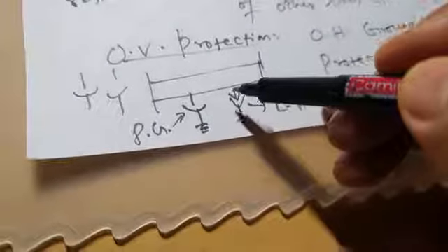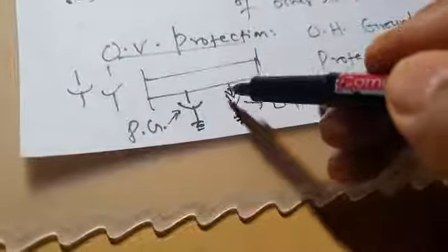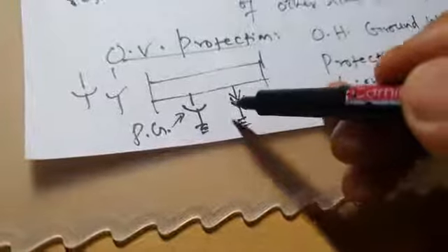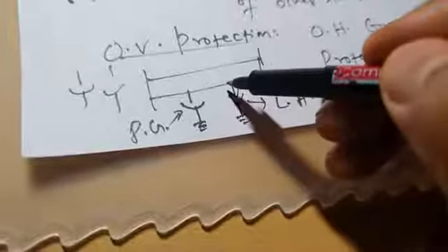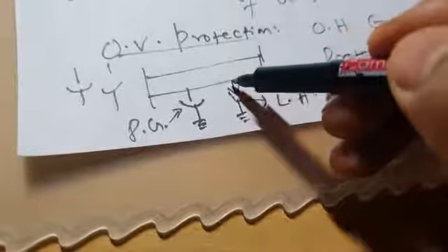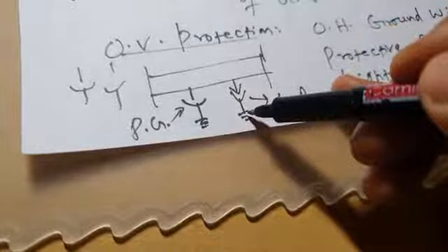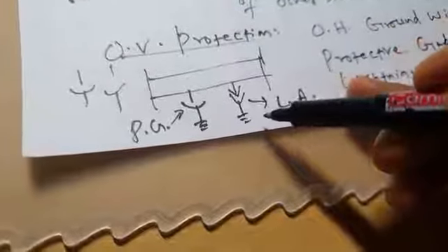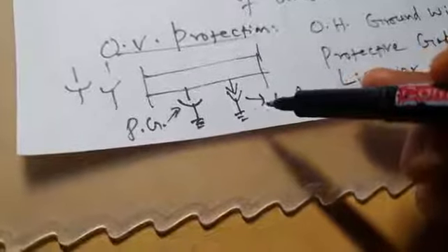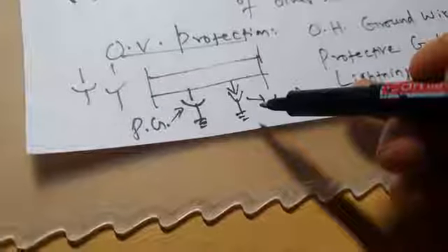That means when there is no overvoltage and normal voltages are there, the lightning arrestor will have high resistance, so no energy will flow through it. And whenever an overvoltage occurs on this AC line, the resistance almost drops to zero, and all the energy associated with the overvoltage is grounded. So you don't need to increase the gap for deionization, and that problem is automatically solved.